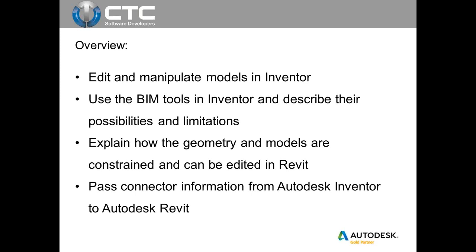Families are like components inside Revit, so your project is built using these families. You could export an ADSK file from Inventor, open that ADSK file in the family environment on the Revit side, and save it as an RFA file, or Revit family file. Once that is done you could use it like any other family inside Revit.